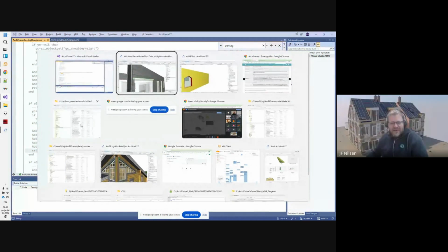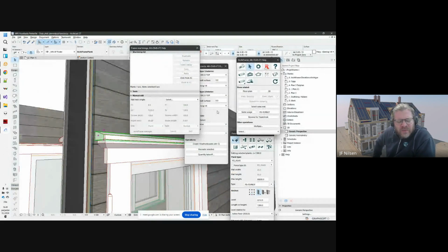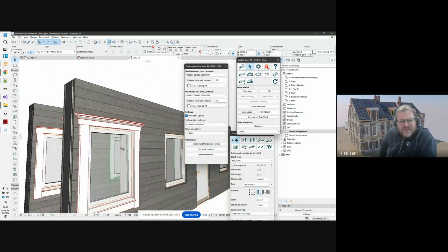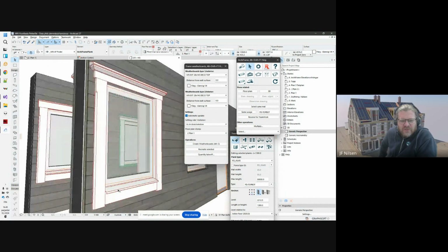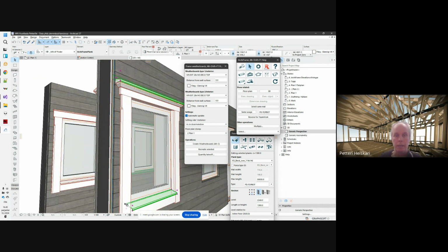Well, I have a question. Can you hear me? Yeah. These weatherboards that you program, do they only work with one defined wall type when it comes to the depth of the layers? You have to make another one if there's thicker or more layers. It's not smart enough to know. That's correct. Yes. So these are fixed profiles, but you can make a library of these.